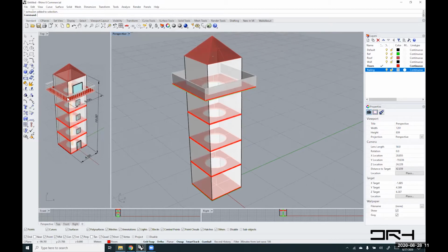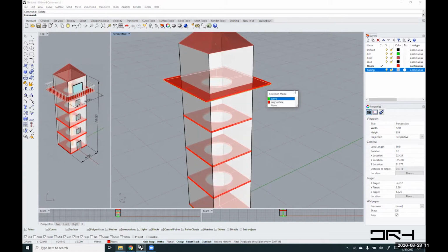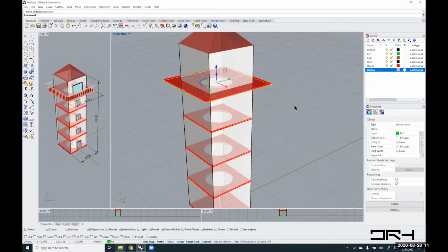Here, I've gone a little sophisticated, and what I did is just created all these little pipes or cylinders. There are multiple ways to do it, and it's not hard at all. So let's try to make those. First you divide your curve, and let's be in the railing layer. You can divide your curve into points and then extrude these points. And once you extrude the points, you can create a pipe around them. So that's one way to do it.